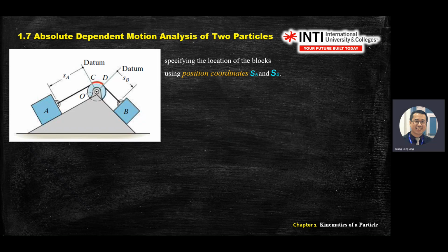You're given one pulley system pulling two objects A and B, and what you start to look at is a bit different from the previous one, is that you'll be seeing datum in a question. With this kind of question, you see pulley, be careful on the datum position. How do you identify the datum's positive direction? The dot and the arrow. The arrow shows you the positive direction that you should use in your calculation. Same with B. For B, we start with this datum. SB is moving down positive.